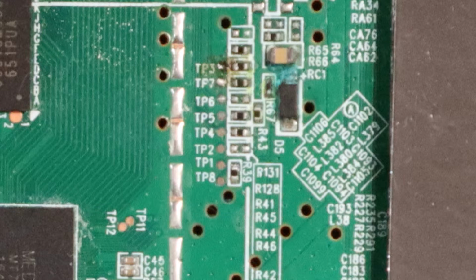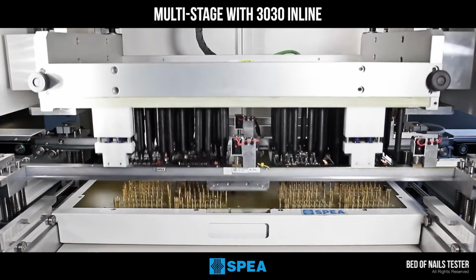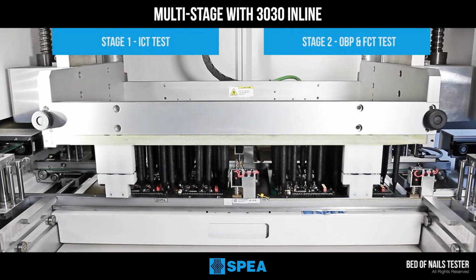The TP in the label probably means test point, and probably these test points are used to test the printed circuit board after manufacture using a bed of nails tester, as the one shown here, where the board is pushed down toward the bed of nails and some automatic test is executed.